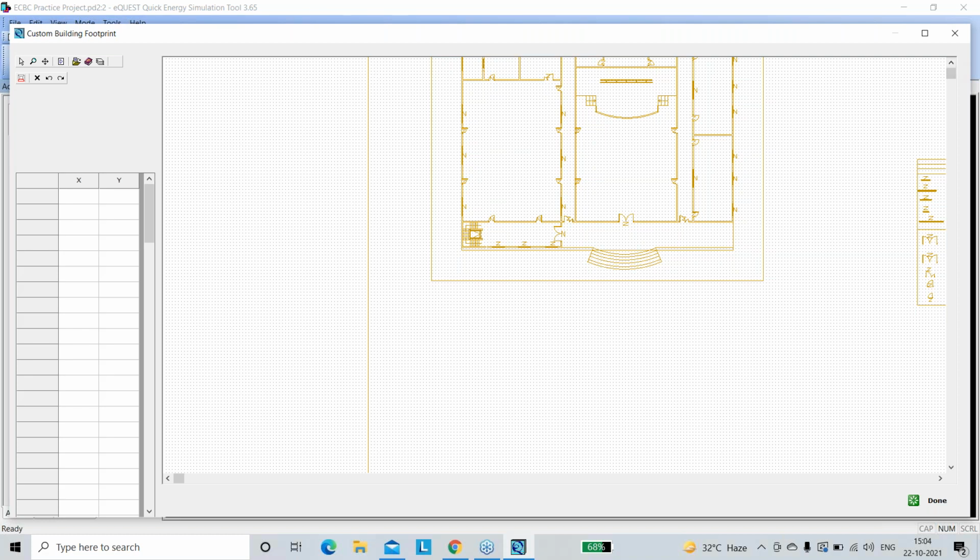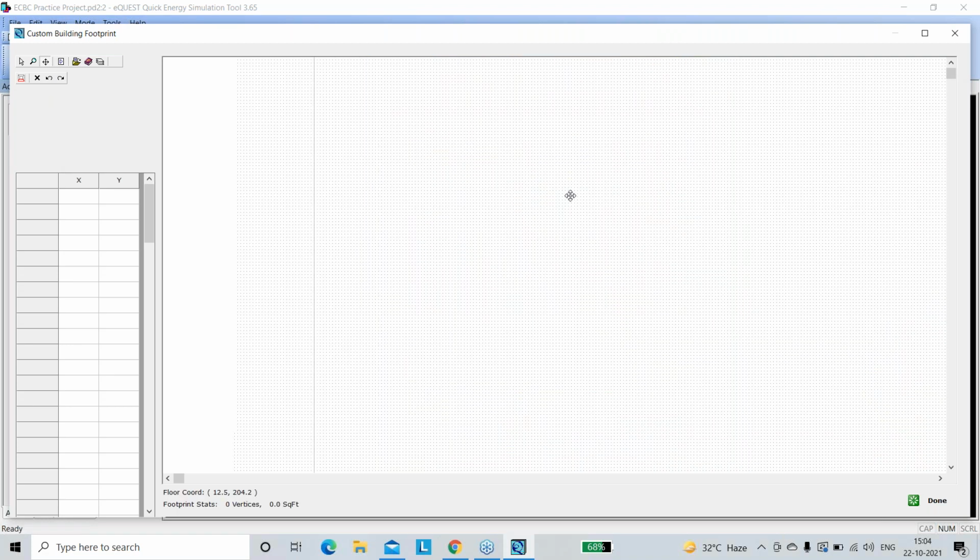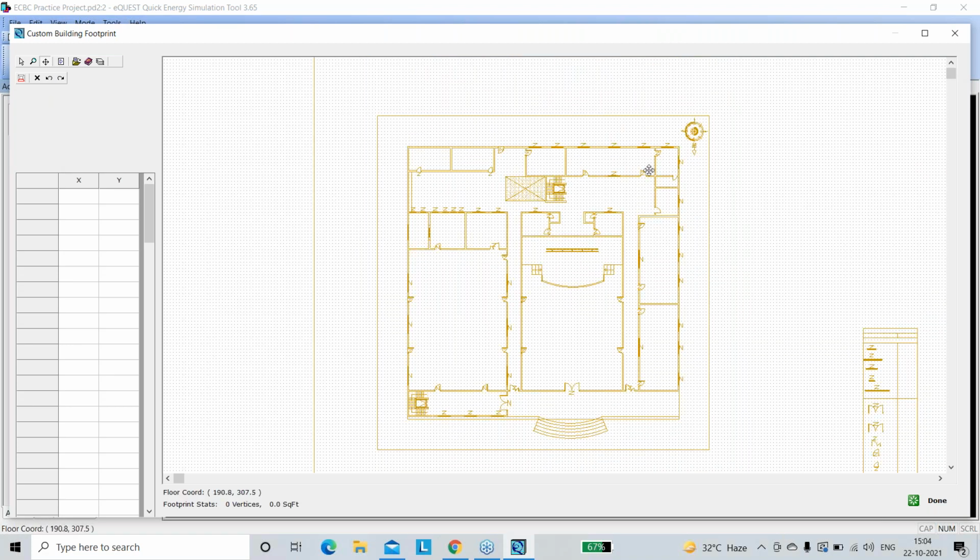What I would do is create just the outline that shows the interior partitions and the zoning, save that as a separate CAD or DXF file, and use that. If you start using heavy files, it will be a headache for you